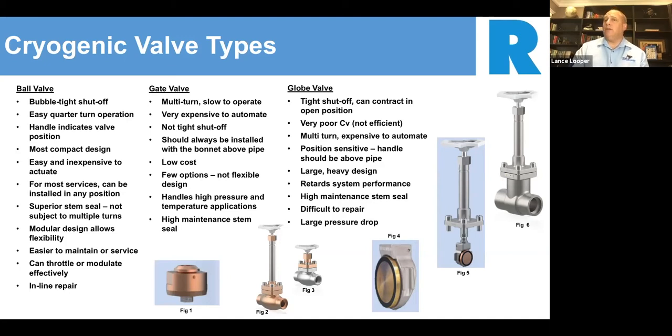My personal opinion about a gate valve, they're really not a 100% bubble tight valve. If you're looking for something that you definitely want shut off completely, it's definitely not the right way to go. There is a little bit of allowable leakage, and when I say allowable leakage, it's counted possibly in bubbles downstream of the valve.